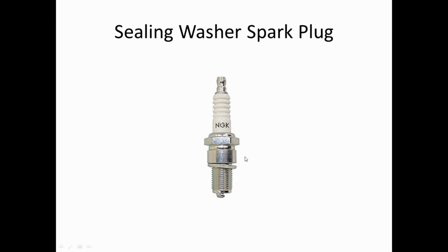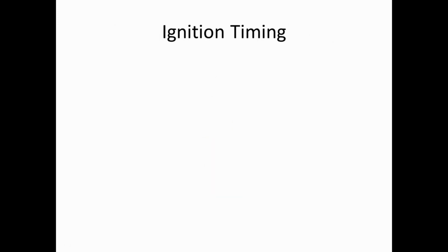For a tapered seal, you only want to turn it about 1/16 of a turn. You don't want to overtighten it. There's nothing to crush on those. And one other thing with variations on spark plugs: some of these have multiple ground straps. A lot of the German vehicles do that. I don't really understand why. Some people believe it'll blow the spark right through all the different prongs. To each their own. It doesn't bother me how many prongs my spark plug has as long as it works.